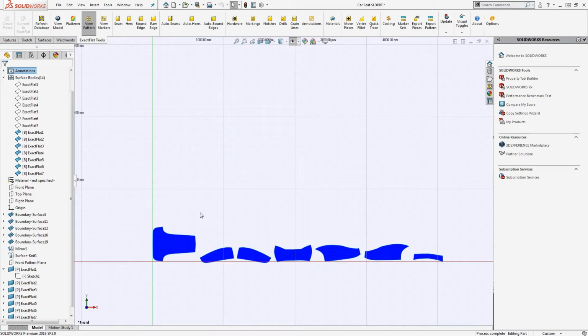So when we compare the accuracy, the first method is to consider the color of the model in the flattener viewport. The more towards white your colors are, the less strain you have. And the strain progresses up to 20% or more, through white being 0% strain to cyan, green, yellow, and red. So that's the primary indicator for the accuracy or quality of your pattern.